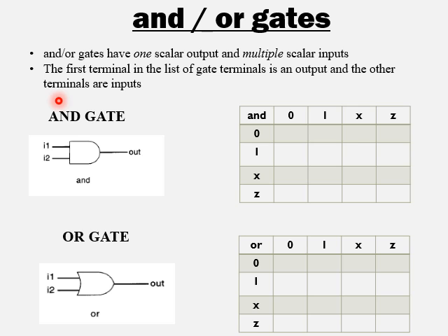The default data type in Verilog supports 4 values, that is 0, 1, X and Z. 0 and 1 are the binary bits, X is unknown and Z is high impedance. This is very much important when you are modeling digital circuits in practical digital circuits. So now instead of 2 binary values in your truth table, it will be considering 4 values.